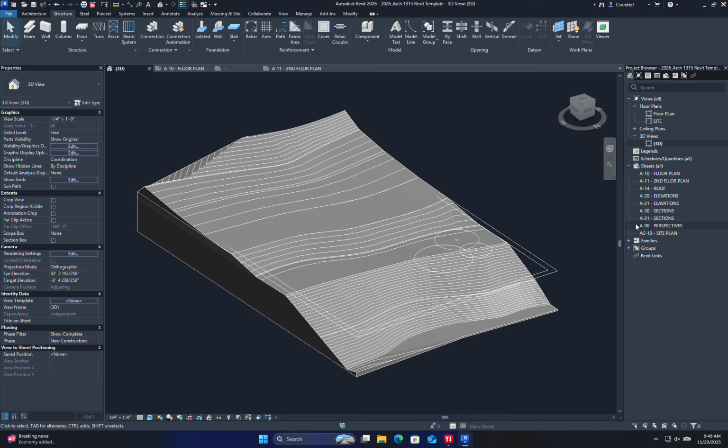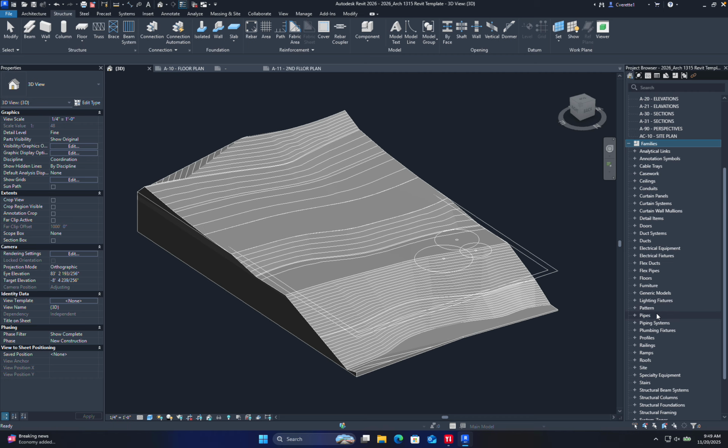And I don't want to explain too much of these and scare you away, but essentially everything is loaded into the project and then picked out like a catalog. So as you'll see, you'll load one door, but it has like 18 different doors of the manufacturer. That's great because I might use one of those doors, and it's really great for the manufacturer to know which door exactly you're ordering. In fact, eventually once I finish a building, I can select the whole building, click on quantities, and see exactly how many doors I need to order, which is a huge plus for a contractor and getting a building built.